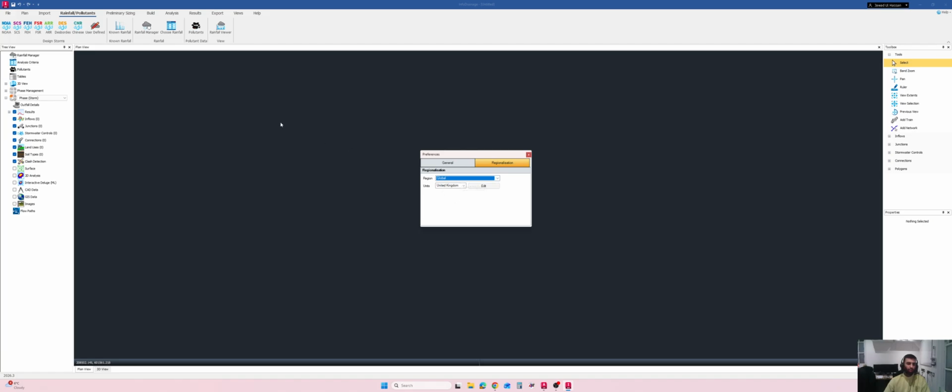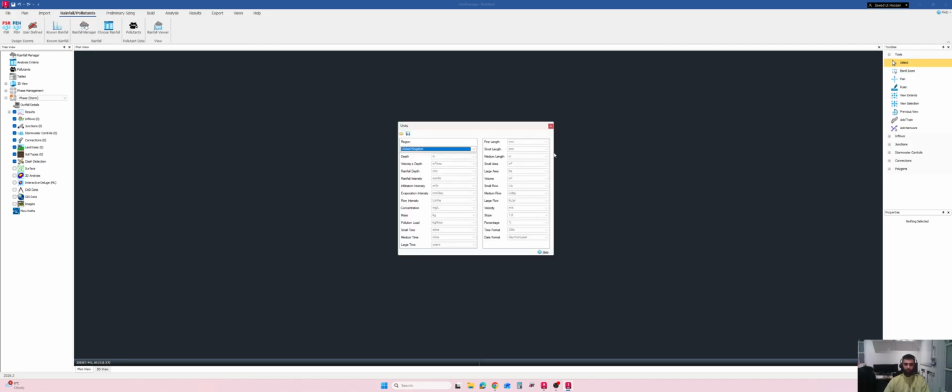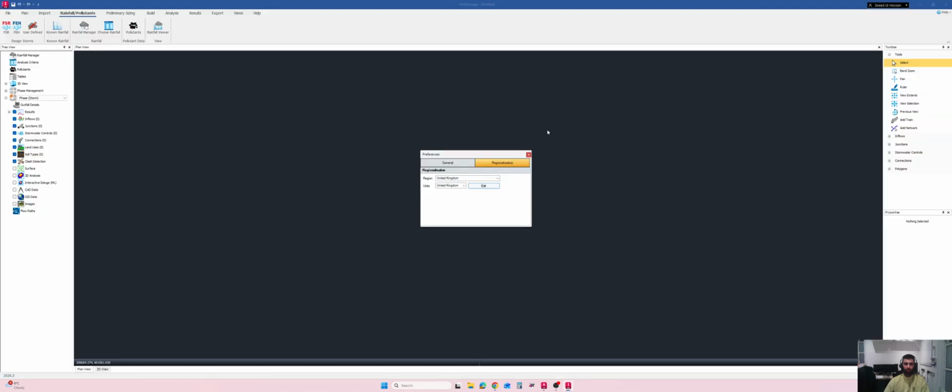Once you have global, you can see all the different design storm inputs that you can use, like Chinese, DES, ARR for Australia, FSR and FEH for the UK, and SES is mostly used for the USA. So this is how you can change your basic settings. I am again going to change it to the UK, and then close it, and have all the units here.